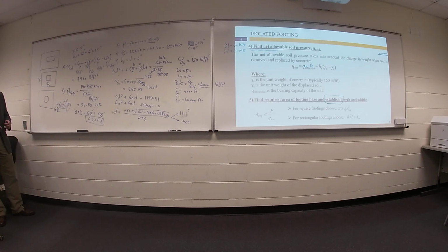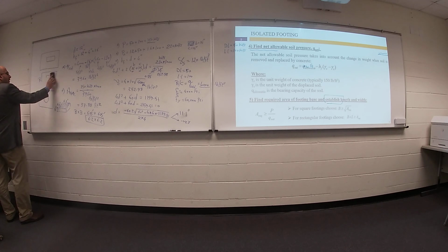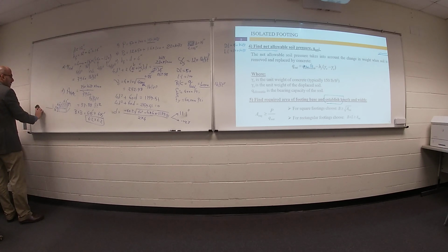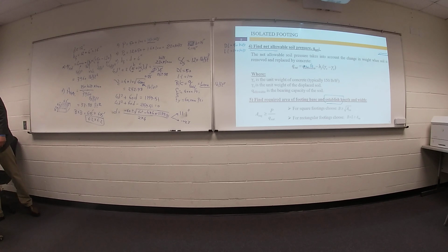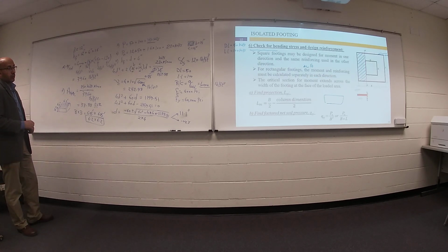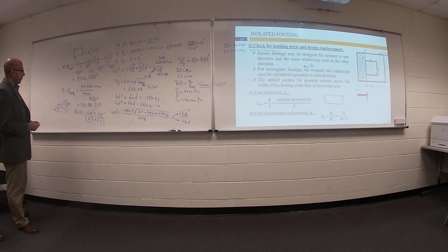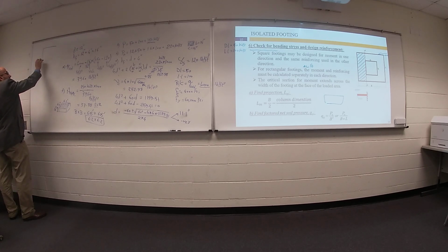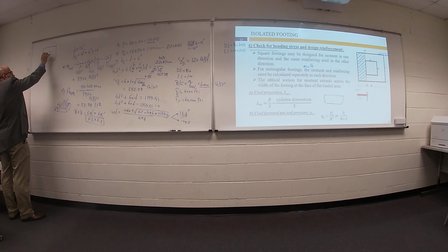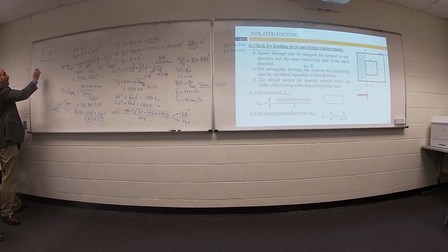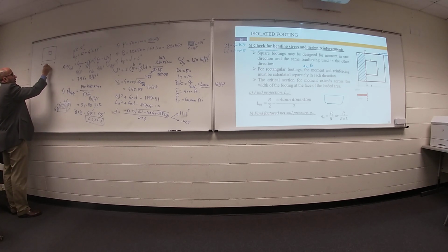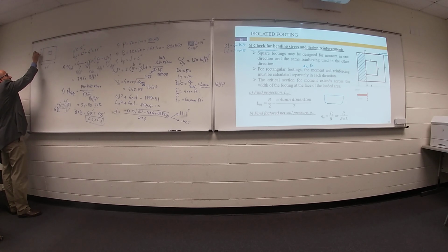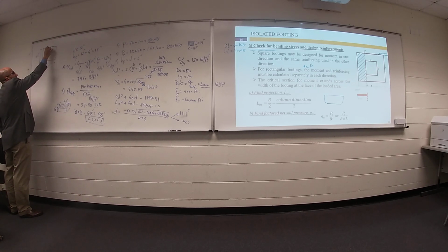Go ahead and determine how much steel reinforcement we need. How much steel reinforcement is required? So keep going. What is the LM? Here is your footing plan. Here is your column. The centroid of the column is the centroid of your footing. This length is 6.2 feet, this length 6.2 feet. This length 15 inch, this length 15 inch.